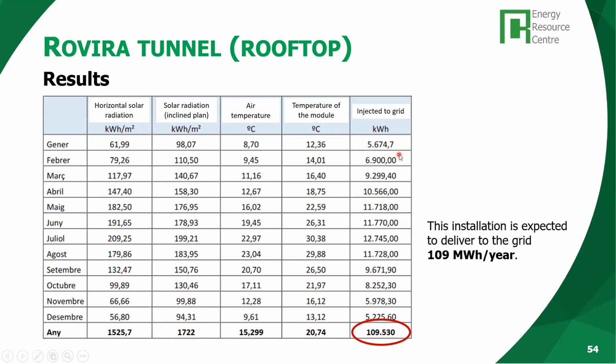If you check the efficiency of the module, understood as the amount of radiation falling onto the module and the output electricity coming out of the module, in the winter this efficiency is higher than in the summer. But in the summer, the solar radiation hitting the solar module is much higher. You see? So this is the key.